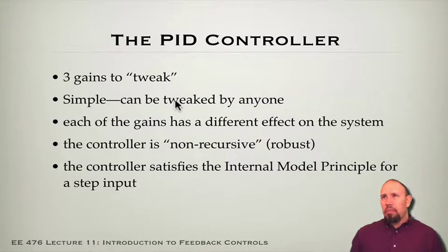You don't have to know differential equations or Laplace transforms to tweak a PID controller. Each of the gains has a different effect on the system. Basically, the controller satisfies what's called the internal model principle for a step input, which is why it's able to track a step input with zero steady-state error.